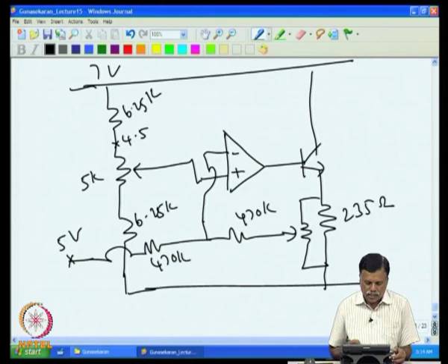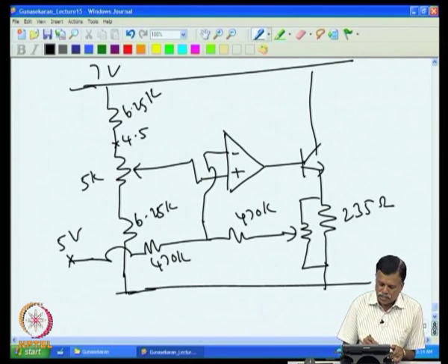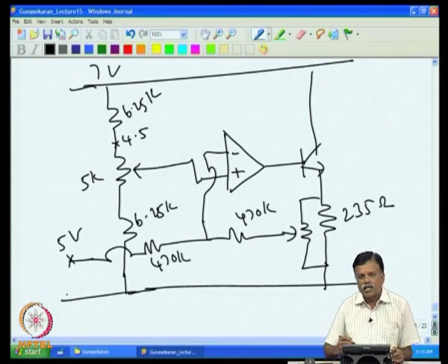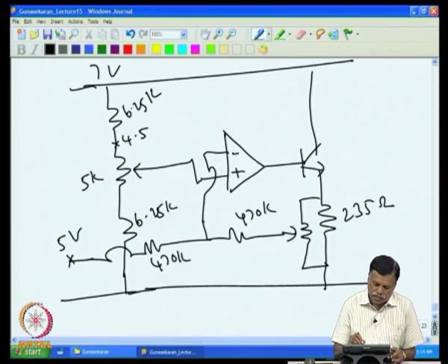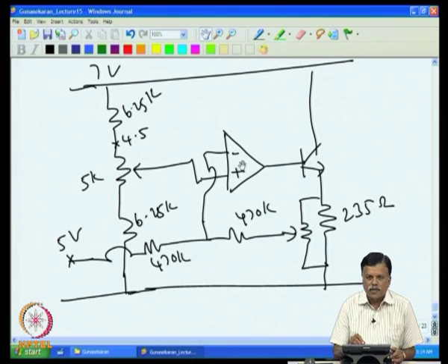So, now we have to calculate what are the errors involved in this, and then we also had to compute that error in terms of current that is flowing in this circuit. Now, if we take this circuit, first we take the simplest one, that is offset voltage drift of this operation amplifier, because this operation amplifier also will have offset voltage drift. So, if there is offset voltage drift here, then what is the current change here?